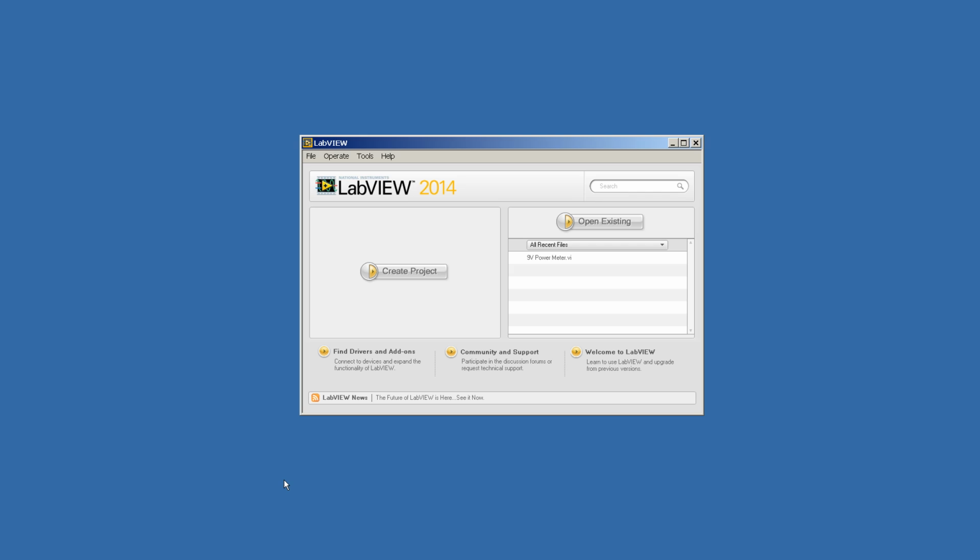In this video, I will show you how you can use LabVIEW to develop a program that will automatically sample the current and the voltage, display the results, calculate the power, and save all of this information to a file. Once it's programmed, you may start the program running and step away to let the instrumentation do the data collection. And then at a later time, you can import that data back into Excel or some other software program for analysis. With the myDAQ device connected to your computer via the USB connection, I'm going to launch LabVIEW.